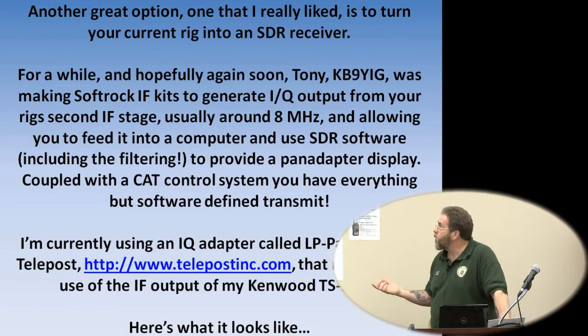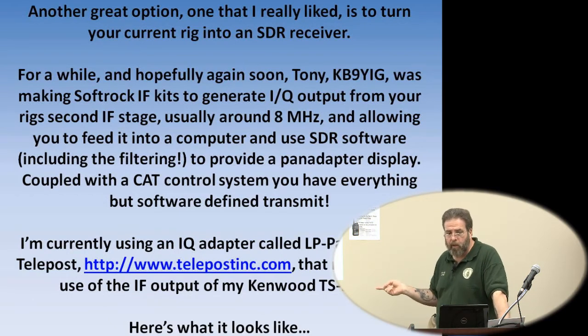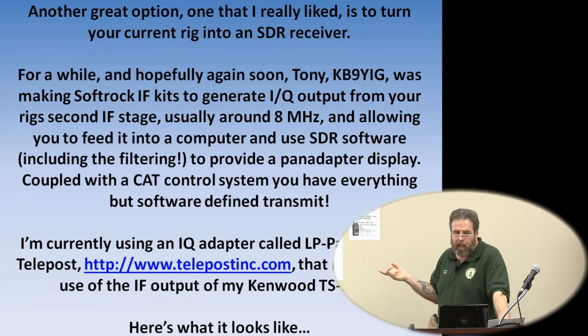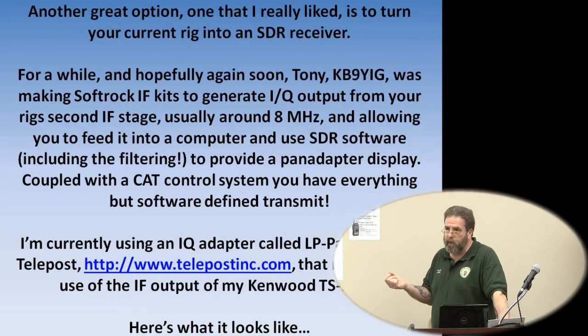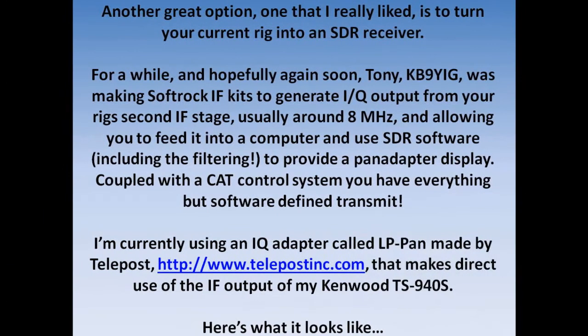Again, I had mentioned earlier about turning your rig into an SDR. Maybe I didn't. Turning your actual rig into an SDR, into the receiver. Tony, KB9YIG, the inventor of the Soft Rocks, he was making a Soft Rock IF version that you could get to make IQ from your rig's second IF stage, which is usually around 8 megahertz. You were able to take that IQ, feed it into a software-defined program, and you had all the filtering of an SDR from your regular rig.